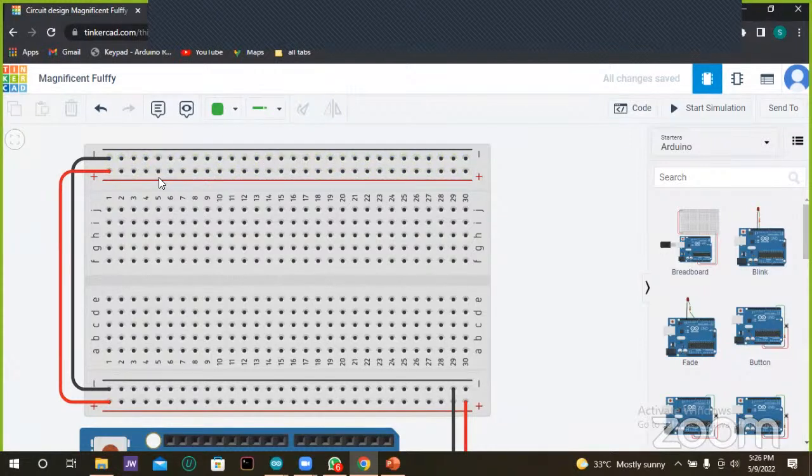You see where the red and the black wire are connected, and the red one, the two places they are connected. So they are all joined together. That is the first two lines. You see where I drop my cursor, all the dots are connected together. So if you are with a physical breadboard, this is exactly how the connections are done inside the breadboard.